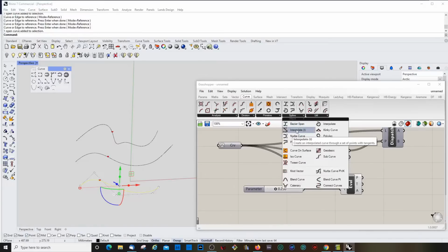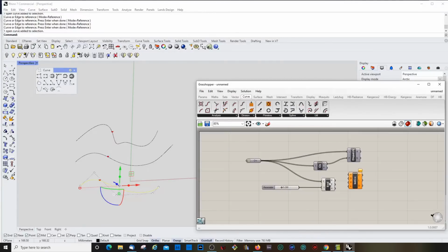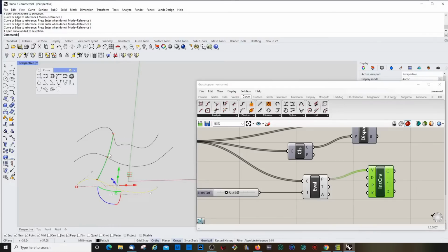For example, you can create curves either with the control points or interpolated. We saw that before in the curve tool. We have either the control point curves or the interpolated curves, which is both just a method. So let's go for the interpolated one. So take this here, and now I just need to place my points, and it created a curve.